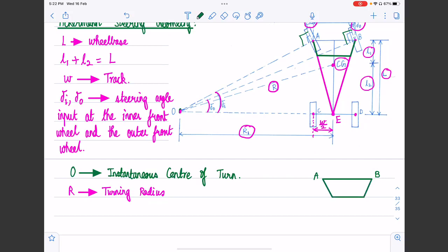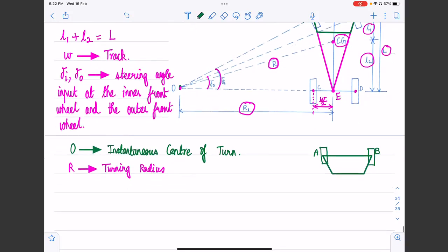This is the shape of the mechanism when the wheels are centered, with no steering. The way it was visualized is that if we project these links, they essentially intersect at a point. This is how the Ackermann steering geometry was initially visualized and developed.